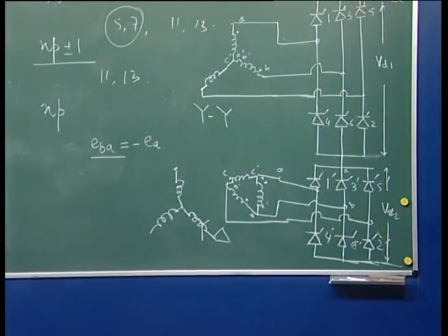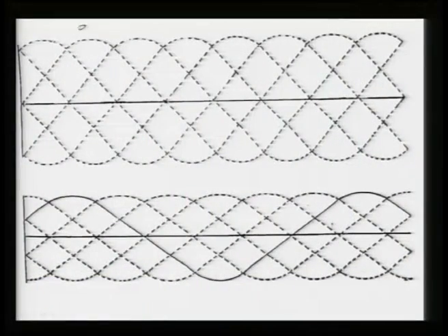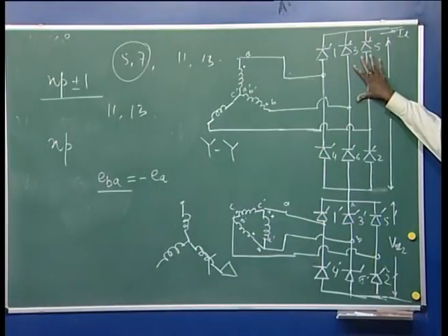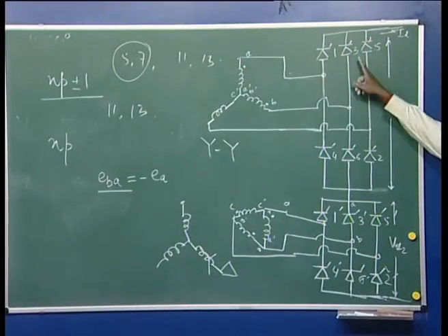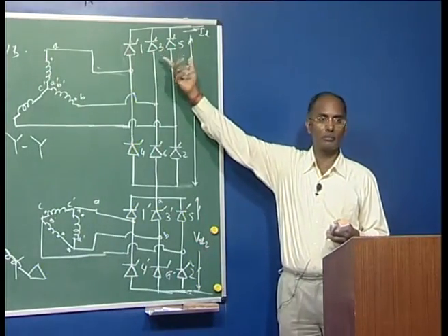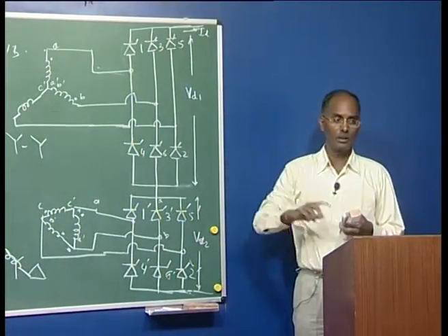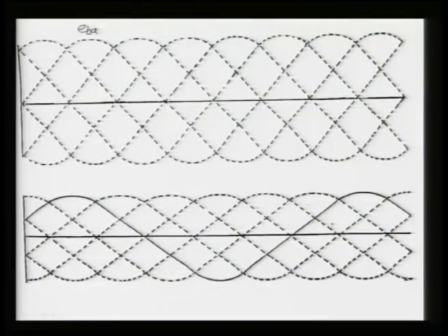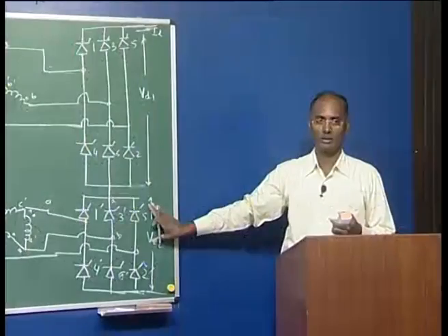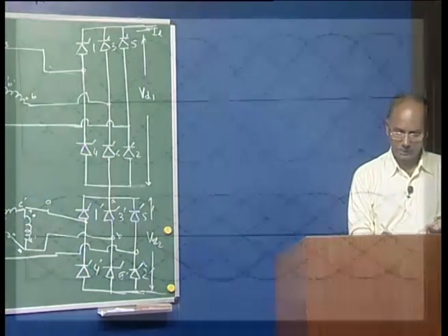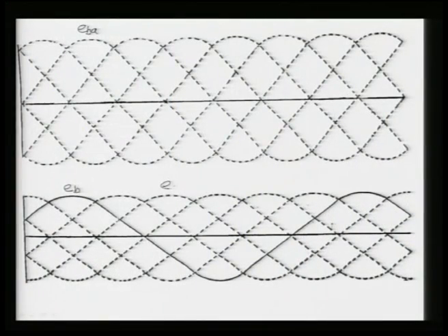Now you can see this was our case. We are again starting here with EBA. It was the case for the first phase, and we took the third valve commutation voltage as EBA because 1 and 2 were conducting. Now I am going to draw the lower voltage for this one. So this was EB, it was EC, it was EA, and finally this was minus EA, this is minus EB, and here we write minus EC.